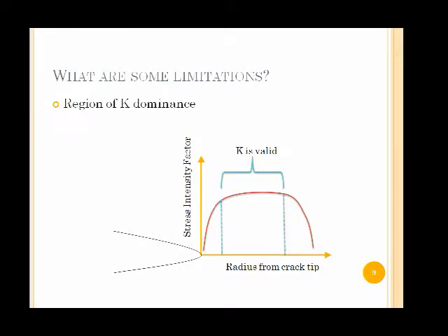Using this idea of a stress intensity factor, there are a couple limitations. We can't calculate stresses right at the crack tip or very near the crack tip because the idea of a stress intensity factor is not really valid. There's a lot of nonlinearity there. In concrete, there's a fracture process zone where these micro cracks are beginning to form. And so our idea of K is not entirely valid very close to the crack tip. However, there's a nice region around the crack tip where it is valid, and knowing that will give us a very accurate prediction of the behavior of the specimen.